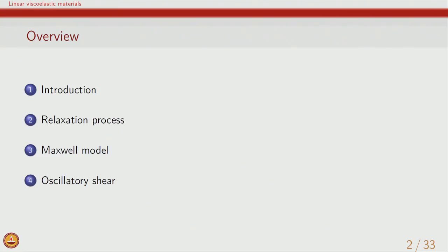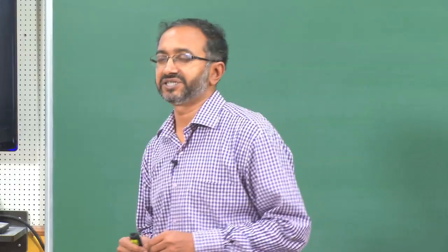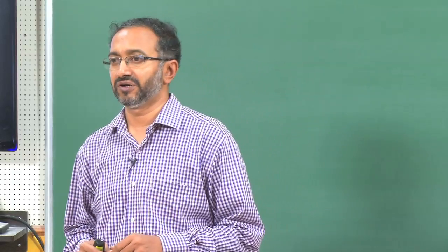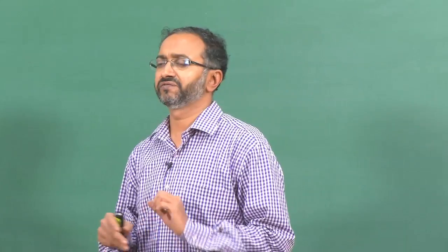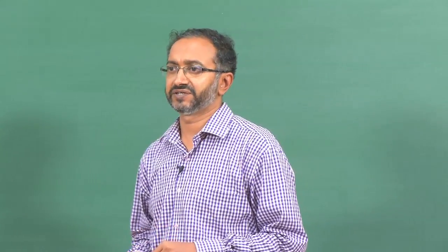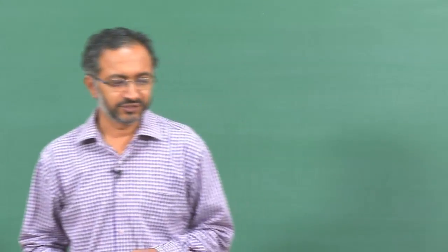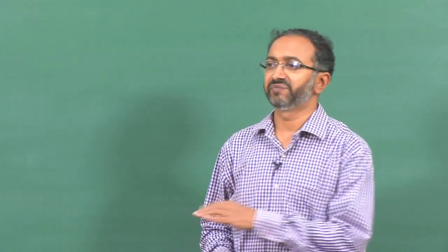And just to understand the viscoelasticity and overall development of several material functions, we said we will look at Maxwell model closely. And in today's class, we will finish up with looking at oscillatory shear, which forms the backbone of rheological analysis for viscoelastic materials. And just to remind us, this is the framework we have been using.